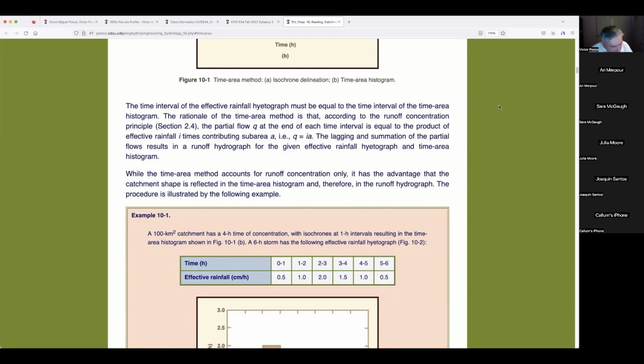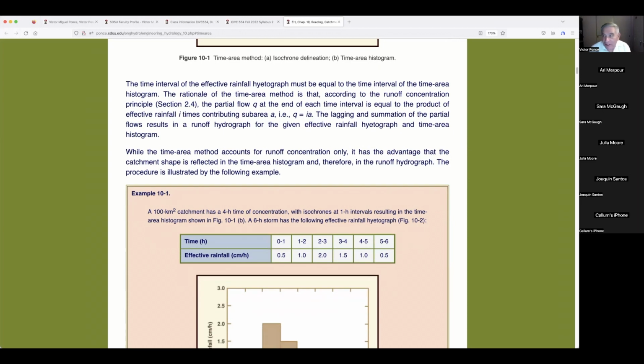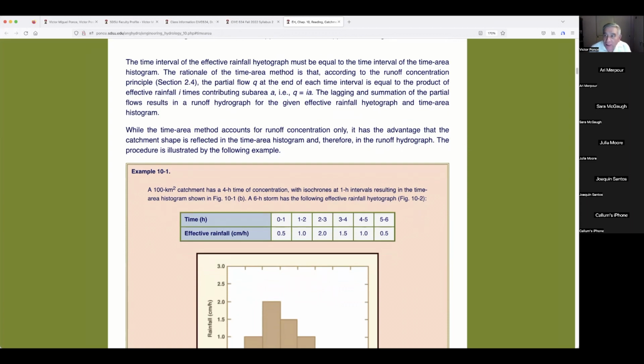There was a basin in Brazil that we looked at that was like a flat eye, where the width was maybe 20 kilometers and the length was 700 kilometers, something like this. It was like a lying down shape, which was interesting because that effectively controls the calculation of the flow. If you're going to calculate the flow, you better introduce the shape issue in there. So nowadays, these calculations are being done with computer models, and the computer model asks you, give me the shape, give me the dimensions, and I'll do the job for you, which is the way it should be, right? So we are introducing the shapes into the calculations.